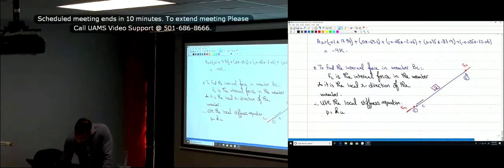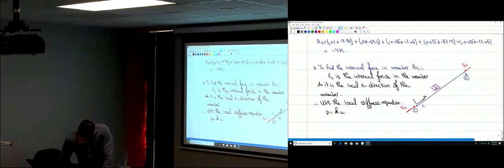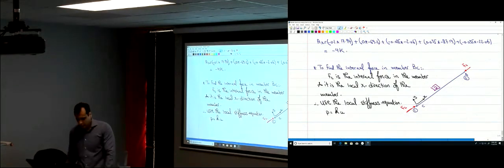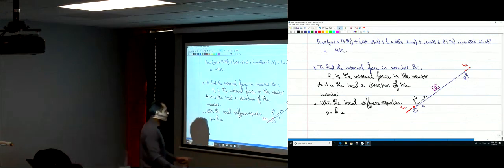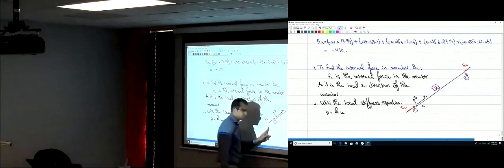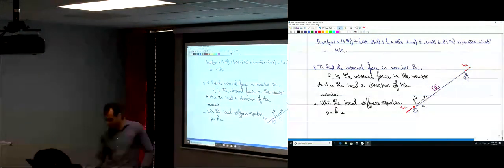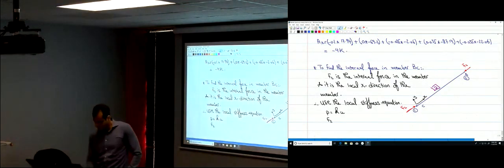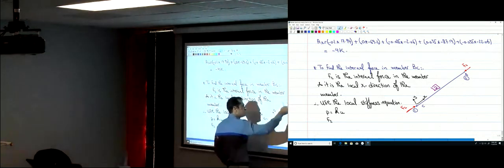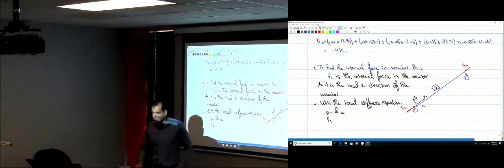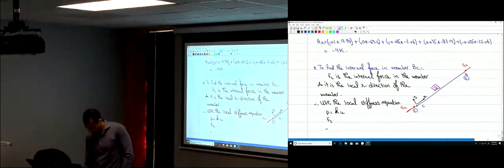That's the x direction, and that's the y. F2 is oriented with the positive x direction, right? So here you have F2, and the force at the far end is in the negative. If this is positive, this is negative, so negative F2 equals k, which is EA divided by L.